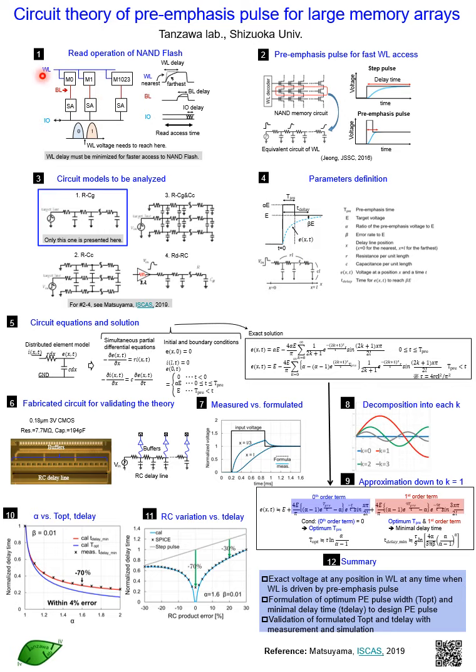Because the word line has significantly large parasitic resistance and capacitances, even if the nearest word line goes high in a very short time, the further cells require some amount of delay time due to large RC delay.